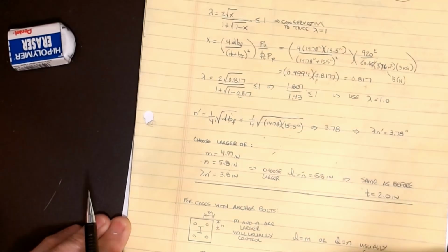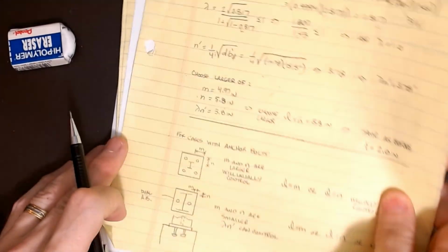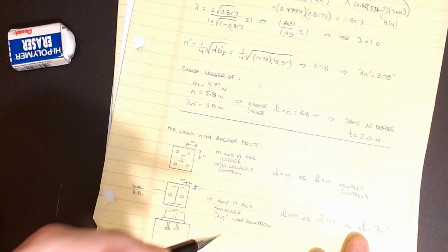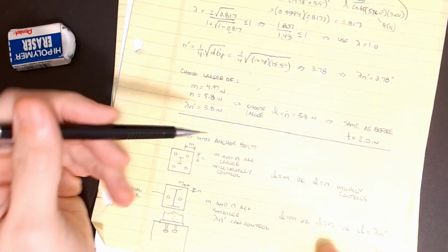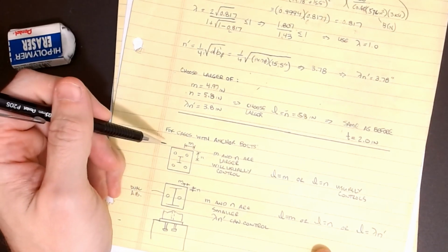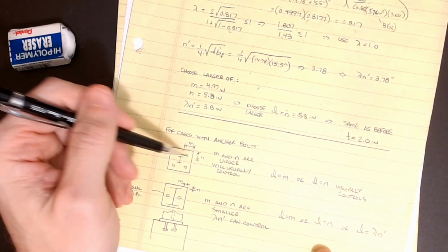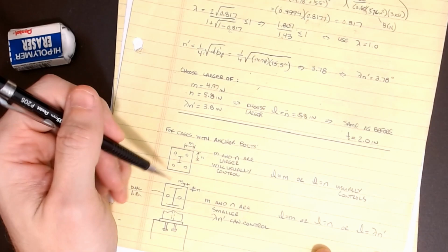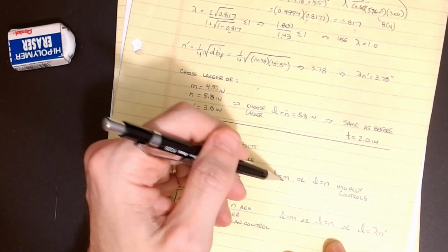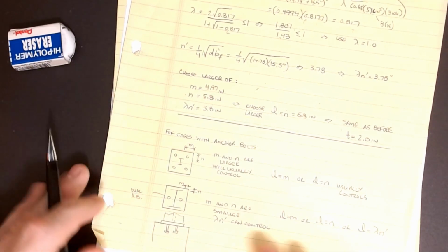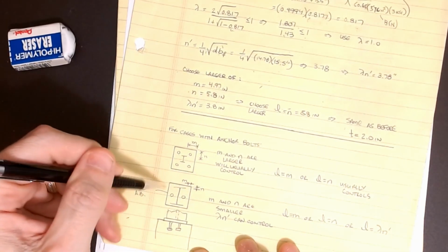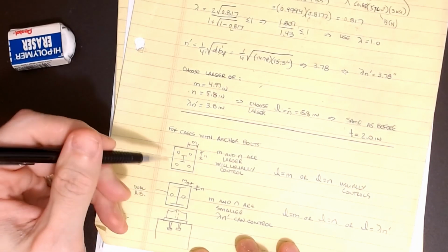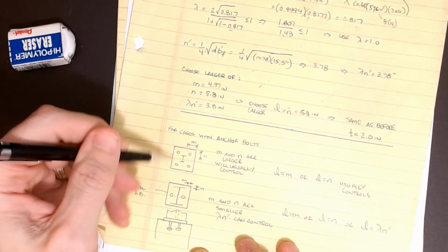All right, now for cases with anchor bolts, what you're going to see is there are some different arrangements and some general thoughts as we conclude this. The calculations are very straightforward. You can pretty much build a spreadsheet, plug in the values, and boom, you've got all of that. Some things to keep in mind: if I have a plate for an I-beam where the bolts are outboard, typically the m and n dimension will control, and that's what we just saw. So L is usually equal to m or equal to n. If my plate is much smaller and tucked in pretty tight and I don't have that 4 inches, because remember we added approximately 4 inches outside of that dimension to accommodate the anchor bolts outboard,